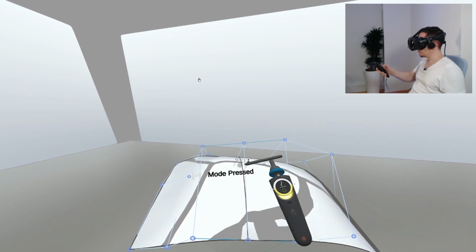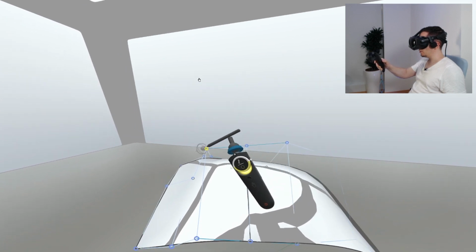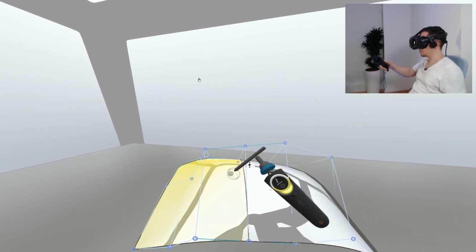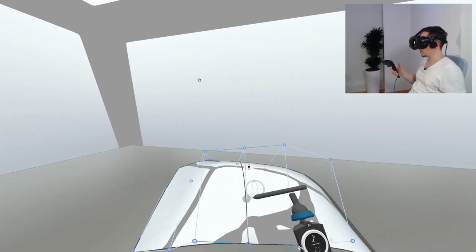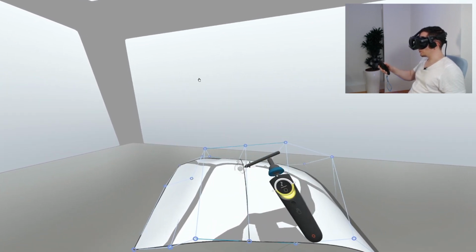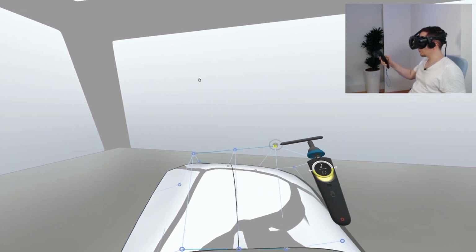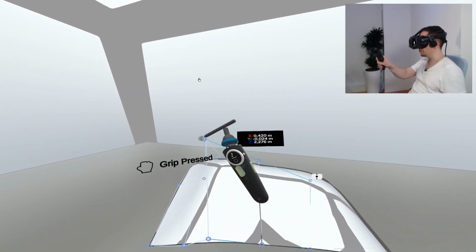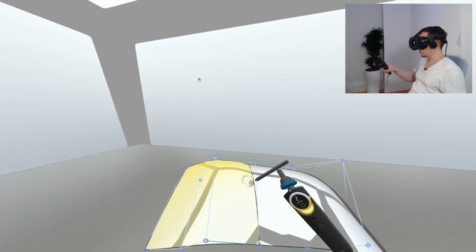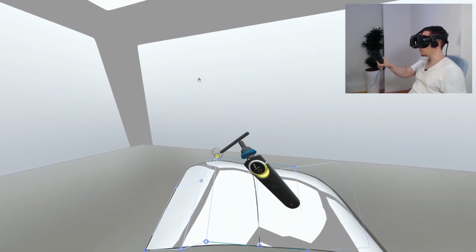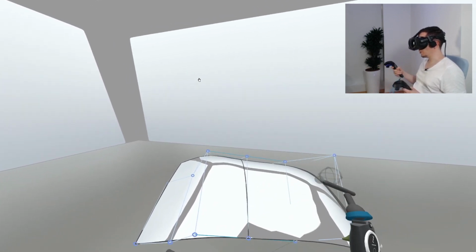So I click it and you see I have the CVs aligned, the transition or connection between the two adjacent patches. You know this icon from the curves maybe. You can also here, when you move this CV, the other one will follow because the continuity requirement enforces a certain dependence of these three CVs among one another.